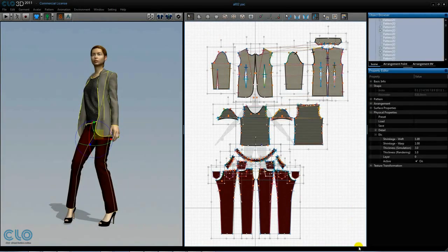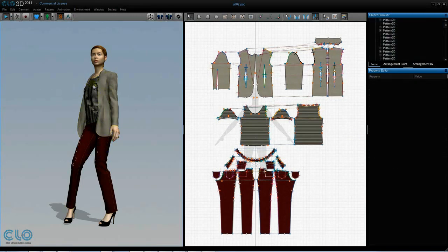They are set at a default value of 3 mm. So we are going to change the thickness to 1 mm, but when we simulate, you can see that because we adjusted the thickness, parts of the avatar peek through the clothing. This is something we can solve by lowering the particle distance, which is ultimately what determines the quality of the